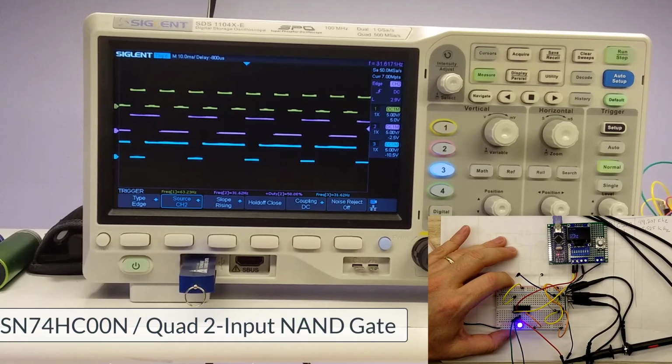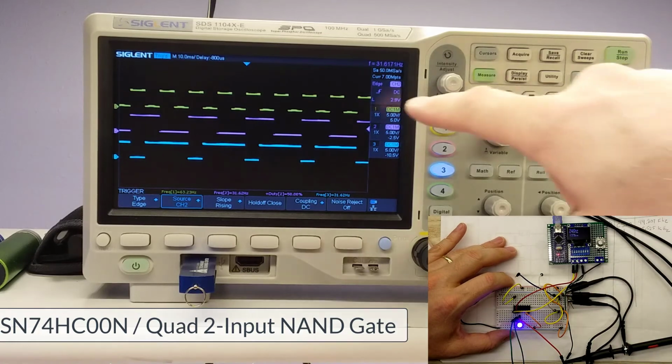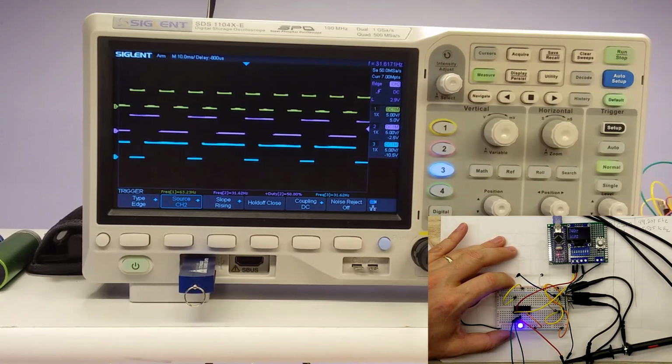Now we have our NOT AND gate set up on the oscilloscope. It's set up exactly the same. The top of the yellow is going to be input 1, the pink is input 2, and the blue is the output. And at this frequency, which is roughly 60 hertz, you can probably see that LED blinking a little bit. And if you can't on camera, I can definitely see it in person.